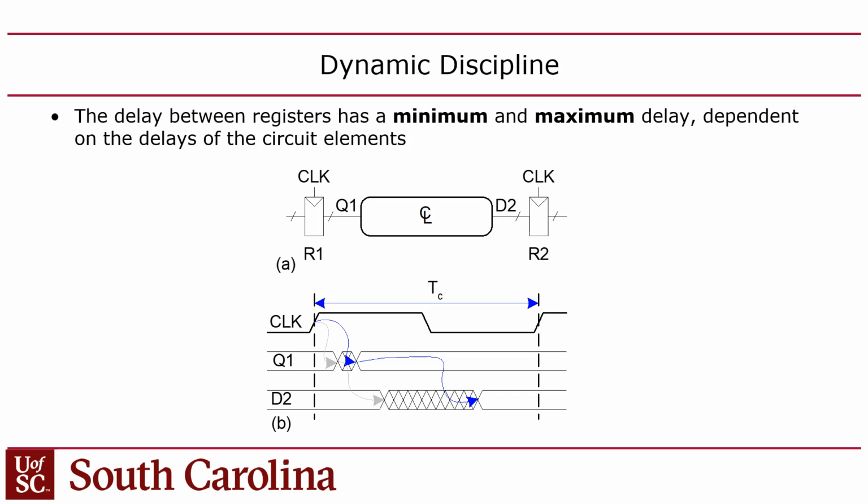So how do you do that? You have to achieve timing closure. You have to generate your circuit in a way that avoids that, and you do it with knowledge of the delay of gates. When I say delay of your gates, I mean the propagation and contamination delay of each gate, which is going to be given to you as part of the technology library of whatever chip technology you're targeting.